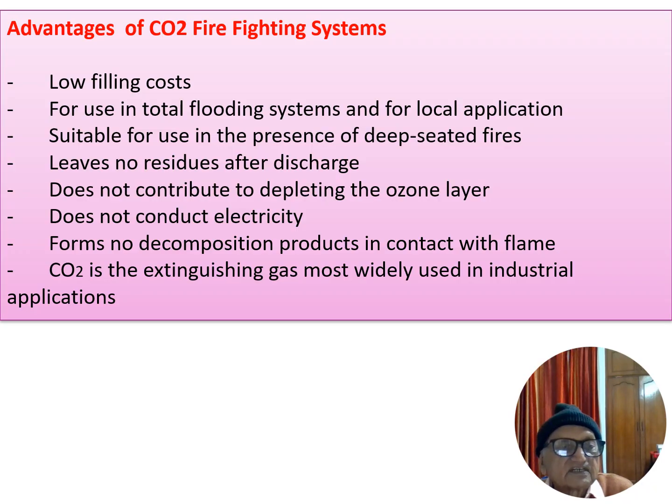Friends, let me tell you the advantages of the CO2 firefighting system. The first is very low refilling cost. Second, for use in total flooding system and for local application, two ways. Third, suitable for use in presence of deep-seated fires. Fourth, it leaves no residue after discharge.